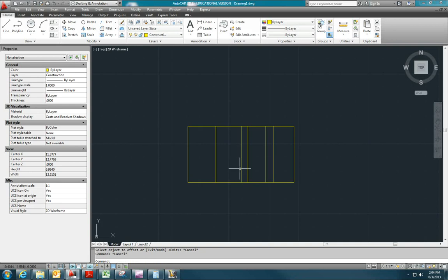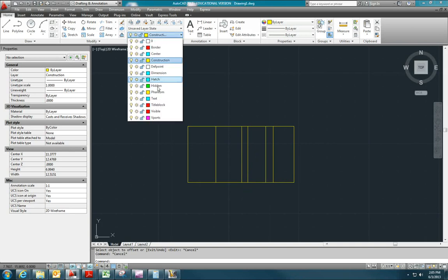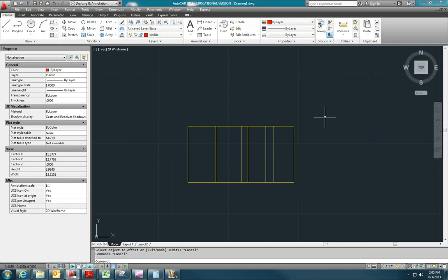Now there's a little bit of a problem with the way I'm doing this. It can get a little bit confusing the more lines you add. So let me just stop here with the amount of construction lines I have and go to my visible layer, and let me actually draw a couple of visible lines to help clean this up. So from the top of this line that was offset by 0.74, I want to draw a line at a 45-degree angle. Now you should have your polar tracking at an increment that will snap to 45 degrees.